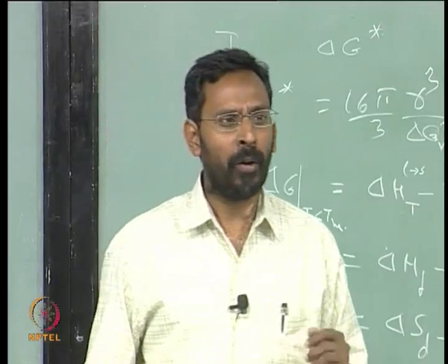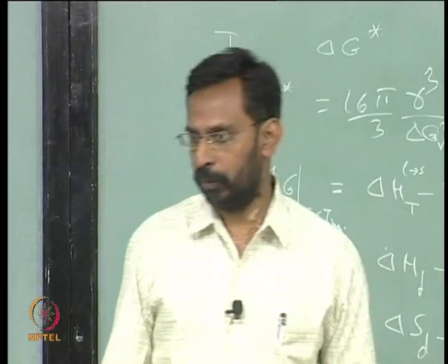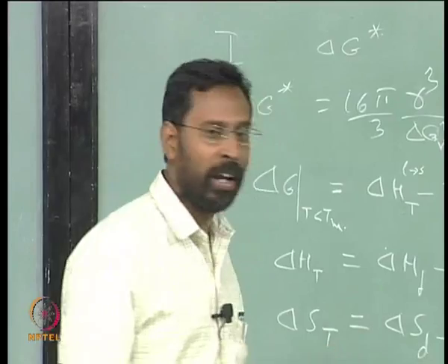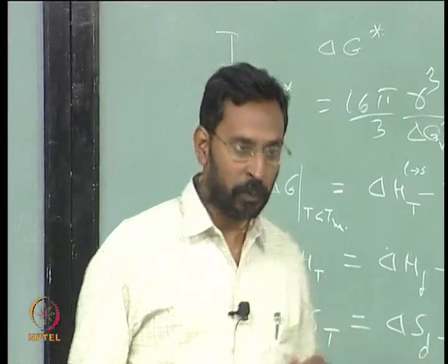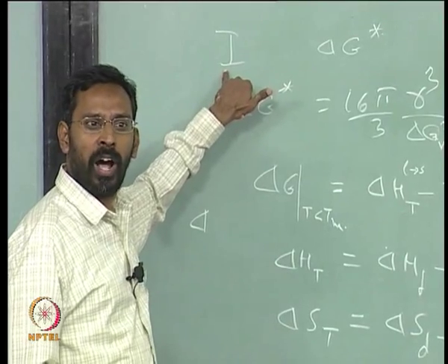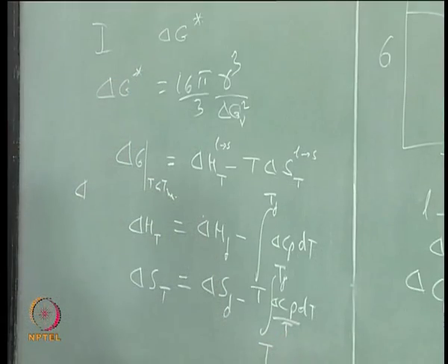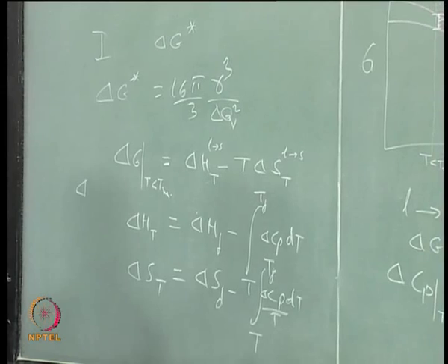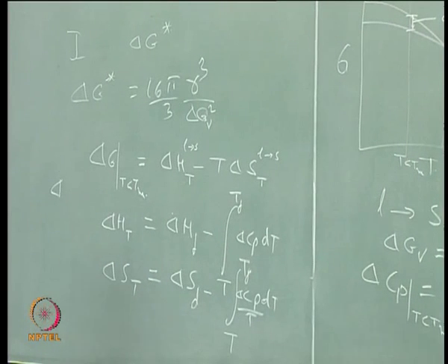For example, how do I know a material has undercooled? I say that undercooling and microstructure are related. Undercooling and nucleation rate I are related. So, I can actually measure the I. How do I measure the I? I need to be able to see how many nuclei are forming, and if I want to physically see these nuclei forming, I should have a transparent liquid in which nuclei are coming.